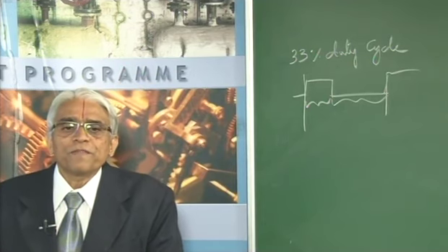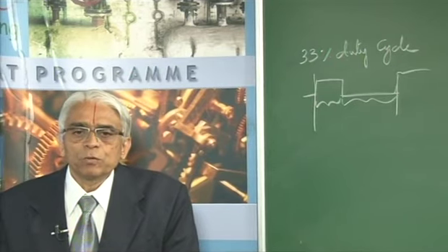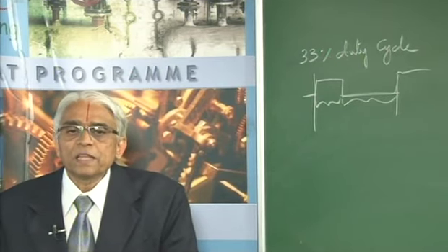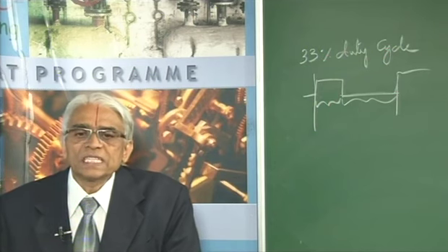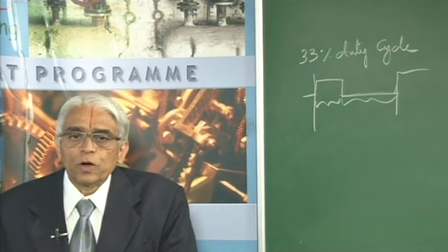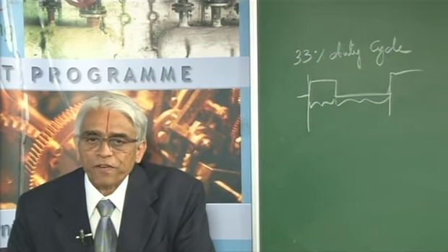So, along with it we have a reset signal. A reset signal is being used to reset the microprocessor. When the microprocessor is reset, all the registers it has got are set to equal to 0, except the code segment register, which is made equal to FFFF hexa.